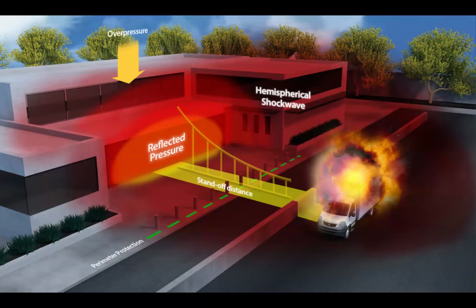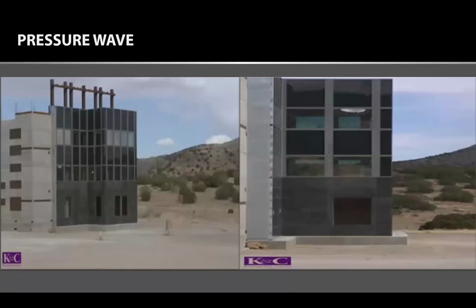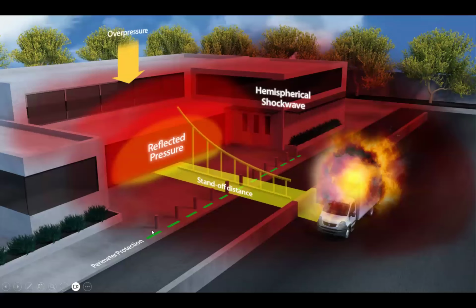Well, the pressure inside that room is changing. It's the same concept applied, but from an external standpoint. So yes, you will be required to have standoff distance and the peak pressure included in your specifications and design details, because at that point, it all comes down to the anchoring to the substructure and the steel framing that is inside the actual buildings as well.